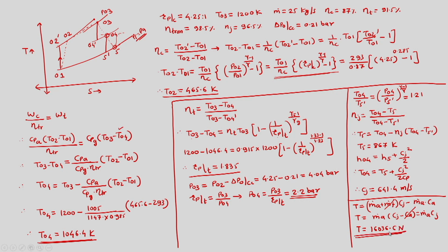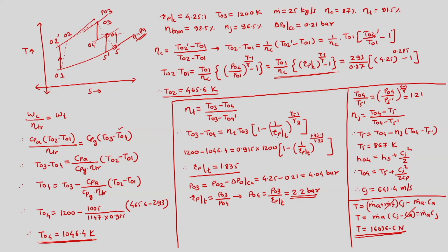So this is the value of the design thrust, where we have considered complete expansion in the nozzle until we attain an exit pressure equal to atmospheric pressure. We did not consider any choking condition. Now let us move on to the next part of the example, which says to consider the choking condition. We had seen that first we have to find the choking pressure, and based upon that we can work up the choking condition.